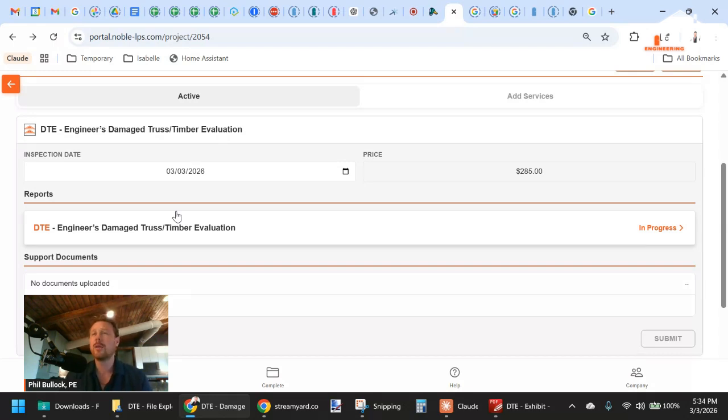Where do we draw the line with this? It's difficult to say. Most of the time these are pretty self-explanatory, but if you go up in the attic and you're like, oh my gosh, they cut every single rafter all the way down the roof to get this AC in, maybe call me or call our team and ask if there's something specific that we need you to gather, or maybe we reject the project. It's too big. Get a local engineer in there to actually go on site, investigate the problem and provide a fix.